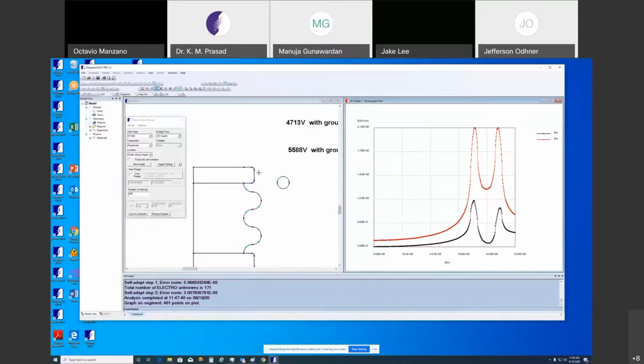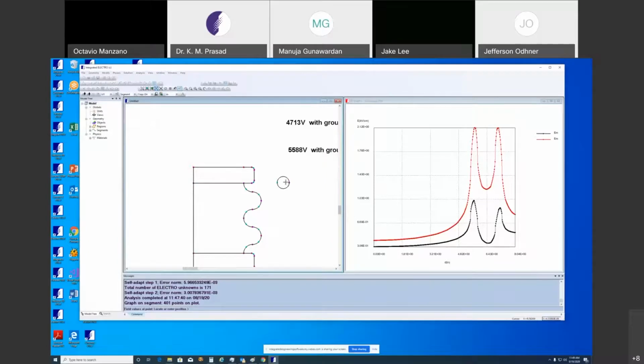Then definitely the fields within this region will be smaller than when you don't apply a voltage. Now this corona ring floats at some voltage which is different from 10 kV. That's why it has got high electric field. Okay, I will close this or let it be like this. I want to see values at a point. What is the value of this here?